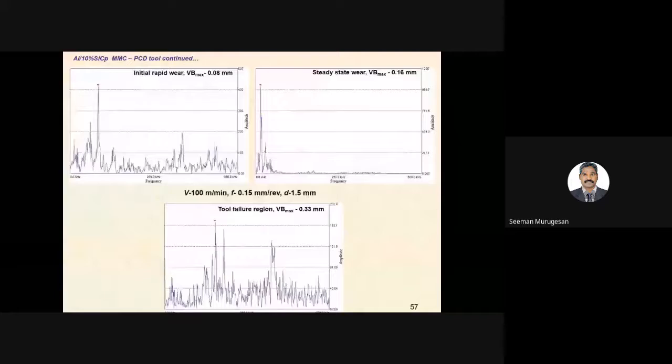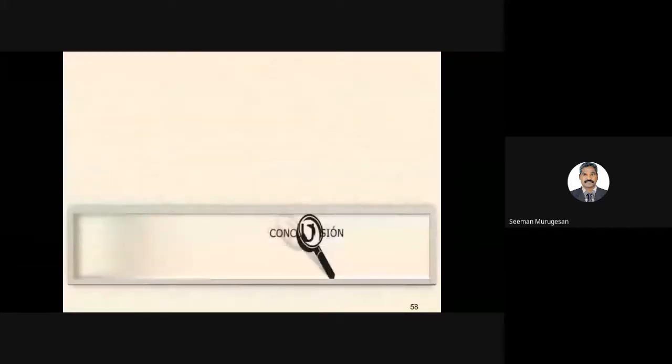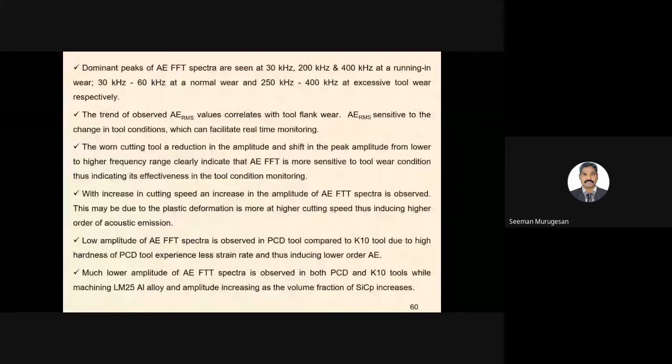Okay. So, in the final conclusion, for the total life criteria, followed by 30 kilohertz and 250, observed the tool flank wear. The change in tool conditions can facilitate real-time cutting monitoring. With the tool wear, the reduction in amplitude and shift of the peak amplitude from the lower frequency range to the higher frequency range clearly indicate that the AE effect spectra is more sensitive to tool wear conditions, thus indicating the effectiveness of tool condition monitoring.